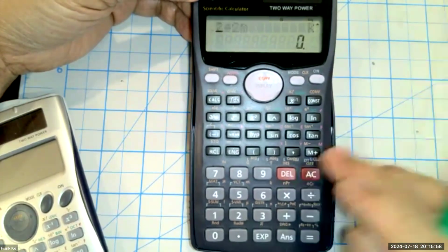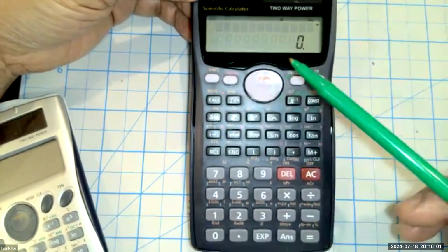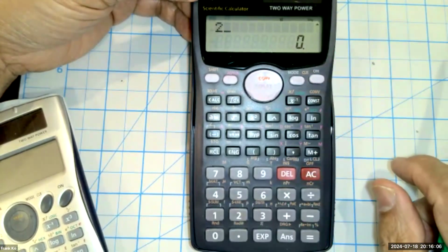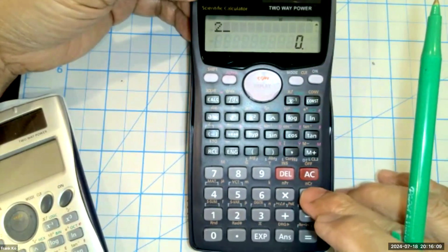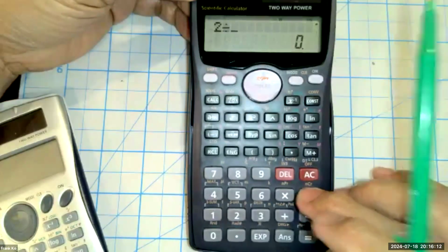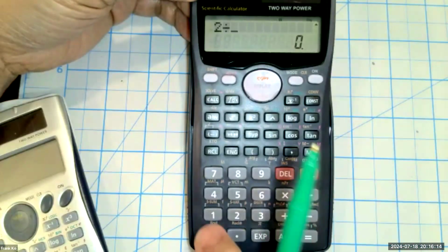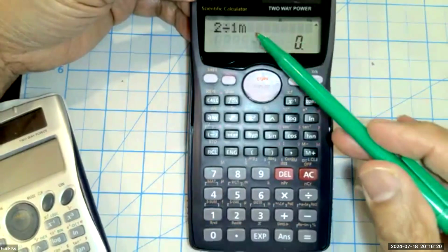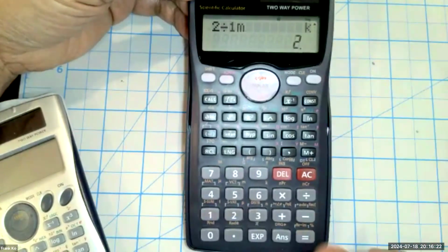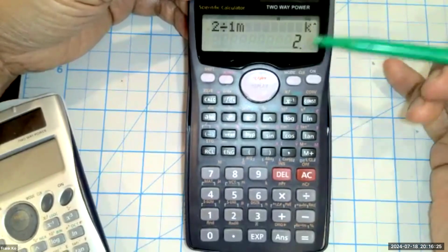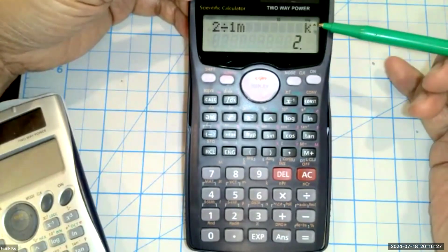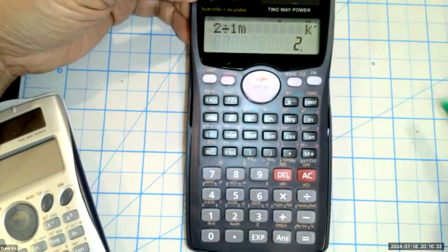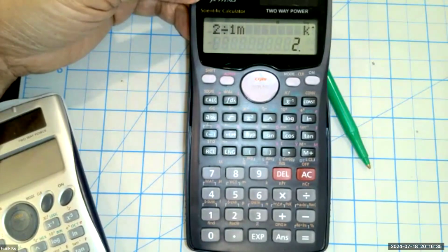That being said, let's do the last one, R3. R3 is the voltage across R3, which is again 2 volts, divided by R3's current. R3's current, we determined, was 1 milliamp. So 1, shift, there's my 1 milli. Then I hit equals. I get 2 kilo ohms. So the value of R3 should be 2 kilo ohms. Write that value down in your journal and let's compare and see what we've got.